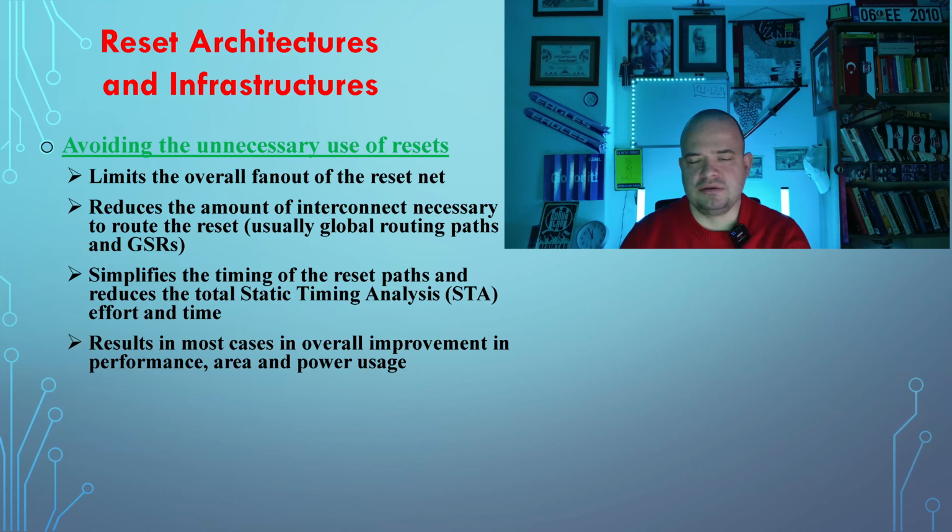I mean, you can still use some resets, but here it is mentioning not resetting each and every signal. If you have some reset signals but their fan-out is quite low, then you will not suffer from these dramatically. Its effect will be really slight.